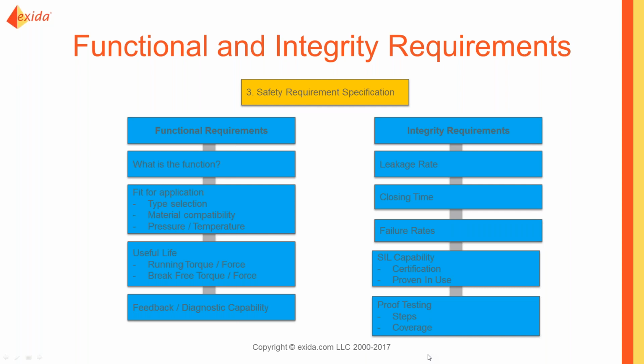Feedback and diagnostic capability, what you want designed into the system, is very important to consider at the conceptual design stage. Will you need to do a partial valve stroke test as a diagnostic? Will you want to do a bottle check or a leak check with your system? What different types of things do you expect to want to do?